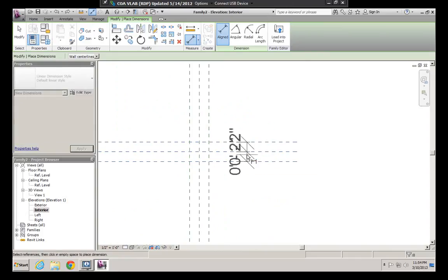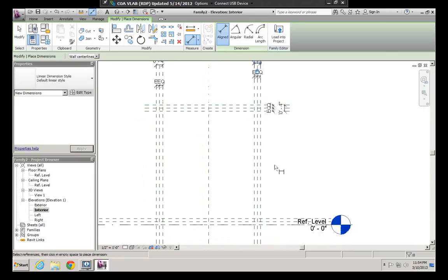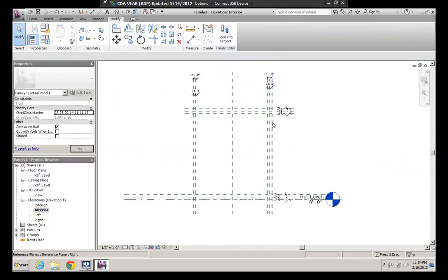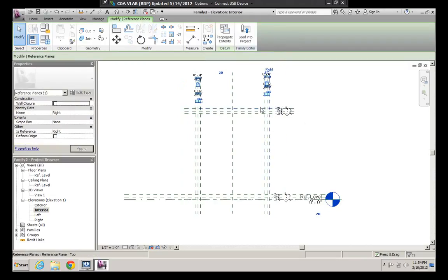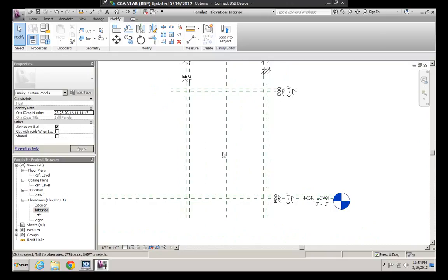So I'll do it here, equalize, and then an overall dimension and lock it. Same thing for here, equalize, and then lock this one, and then I need one for the bottom. And lock it. Now let's start flexing our tile. This seems about right. Let's flex this one. This is about right, so we could go ahead and model something inside of this now.